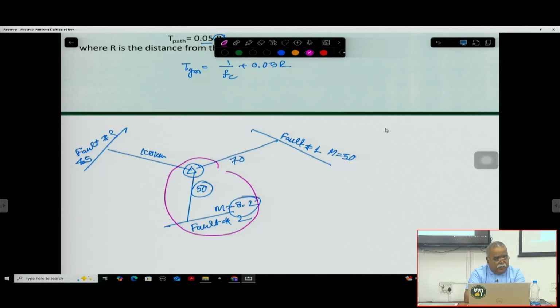Okay, but definitely at that site they need to do all the borehole information, or the seismic cone penetration test, or all these things, to get the seismic velocity and density calculations. They have to do that. Okay, if you are building a big structure, you have to spend the money for this. If you have a 2 to 3 story structure, the engineer says, okay, I can do these things without any issue. So that will be fine.